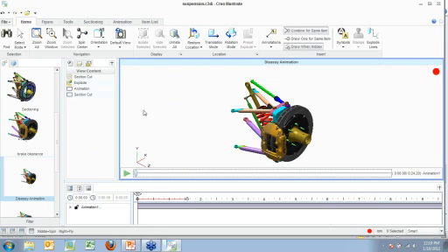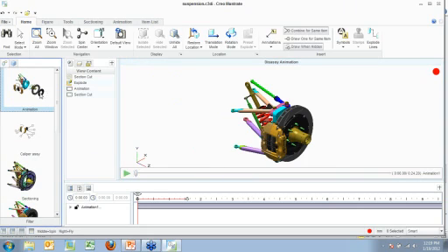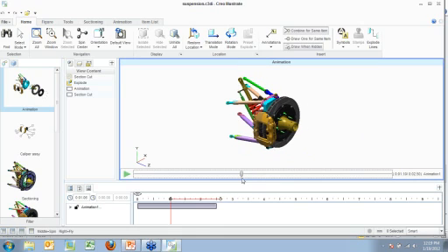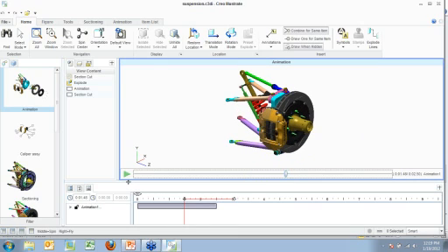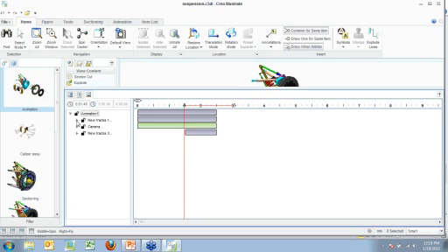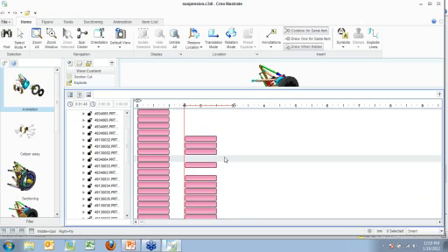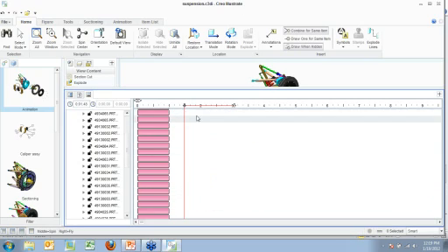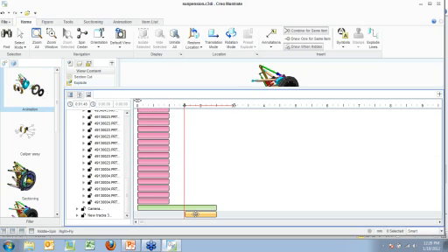So, I showed you some of the effects there. If we'll go up to another animation here, this is one where I just had it come in and do that. Like, let's say I don't want the caliper to explode off of there. I want to leave it. I want to stop it in this state. Well, it's really simple. I can come in about a second and a half. Drag this up so we can see a little better. Expand out my animation. There's all my components. I can go in, select all of them, hit delete. Now that movement, this bar signifies a movement from 0 second to 1 second. Now all of those movements are gone. Delete this one down here as well.